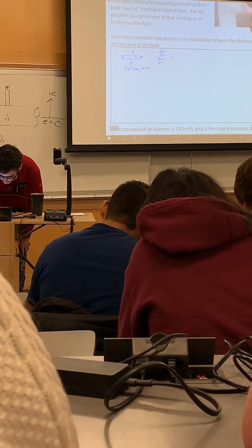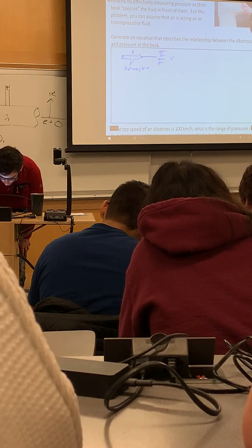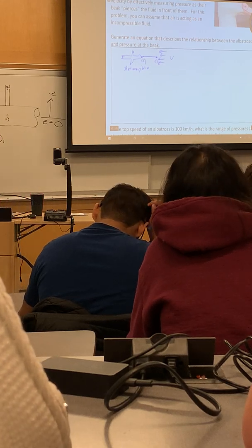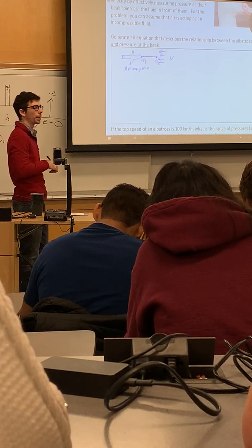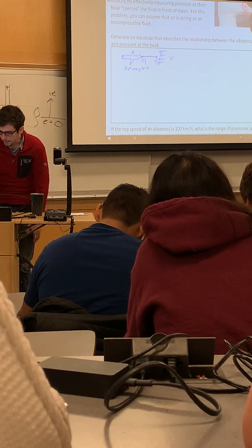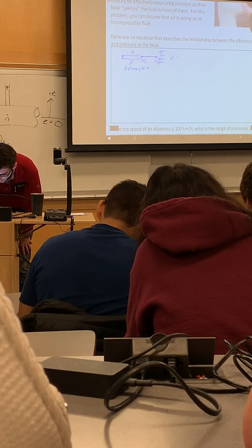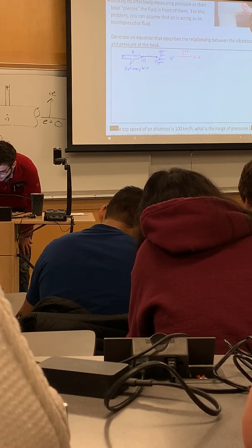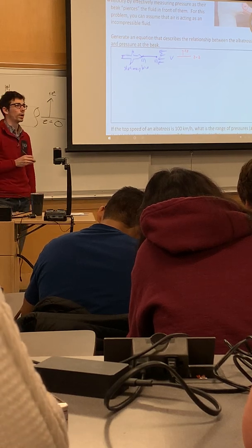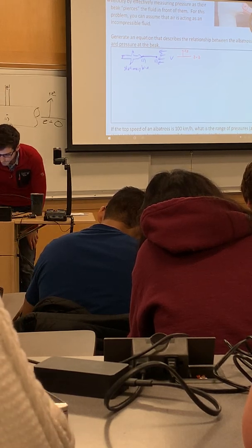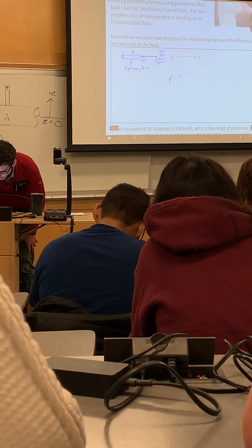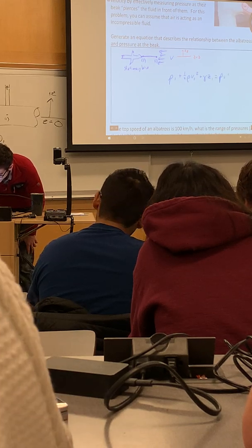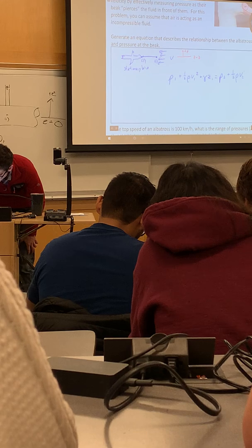So, similar to our previous example, we can say that there's a streamline that connects the bulk fluid with a point just upstream of that stagnation point. Right. And if we draw a datum at z equals 0, with this being positive z, we can apply the Bernoulli equation 1 or 2. So P1 plus 1/2 rho V1 squared plus rho g z1. You'll be able to write this equation in your sleep by the time you're done with chapter 3.